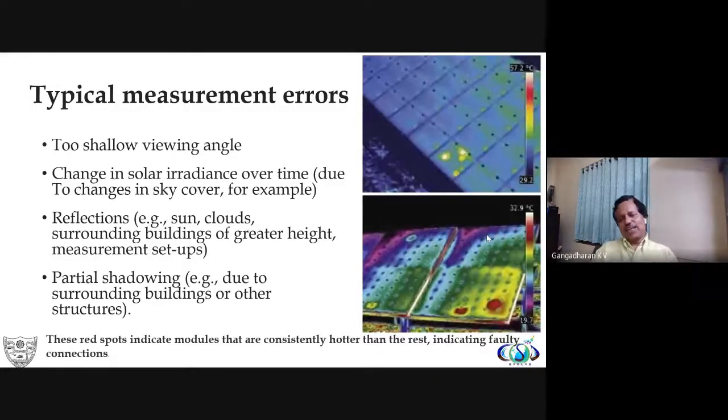Maybe after breakfast or tea, we take another reading, and in the afternoon we take a reading, and in the evening we take another reading. Because each flight can only do 10 to 15 minutes of flying, only possible in the case of normal drones. And that too, we may not risk taking it to something like 75% of the battery of the drone. That means generally we keep it at 60% of the battery we consume, and then we abort the mission or plan the mission in such a way that we take that much reading and come back. Then it needs to be charged, then we take the reading.